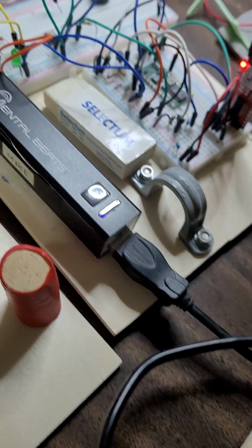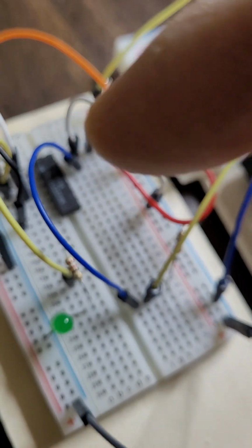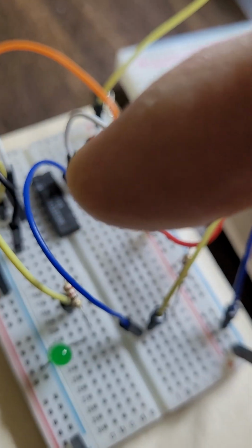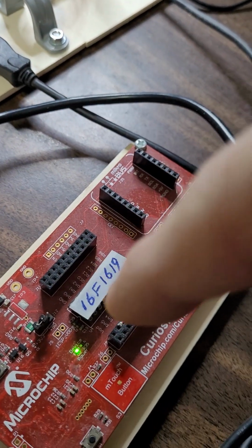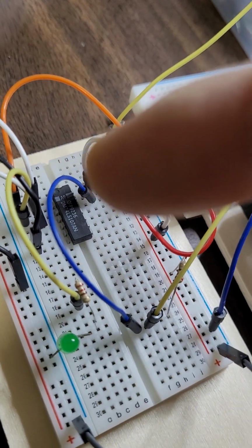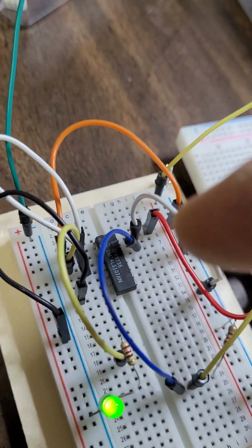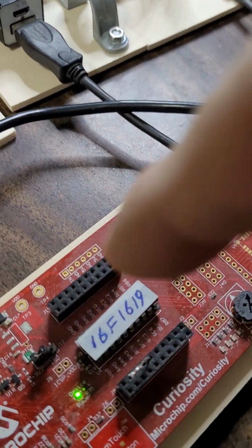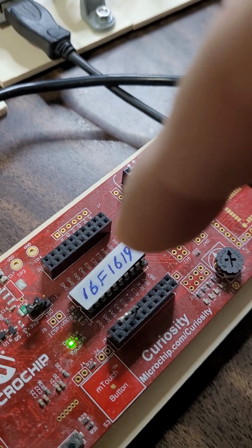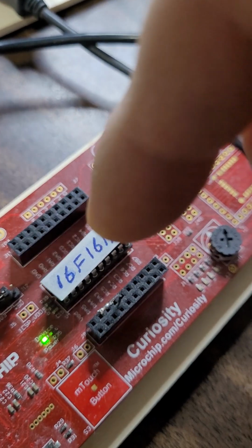As you see here, this is hardware. This one is a JK flip-flop outside, not built in, from Texas Instruments, the 74LS107. It is performing the same job. So this is hardware, and this one is done by configuring the CLC of the microcontroller.